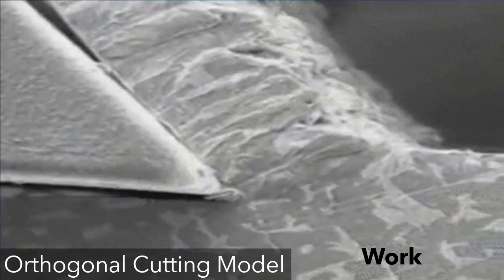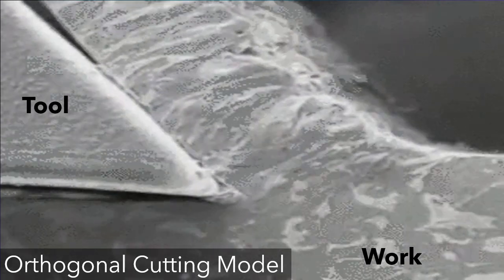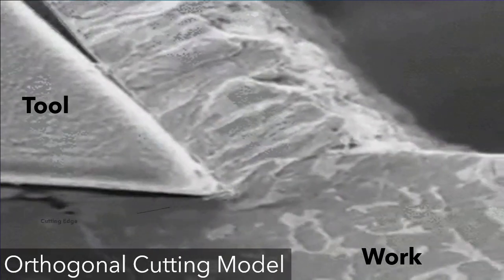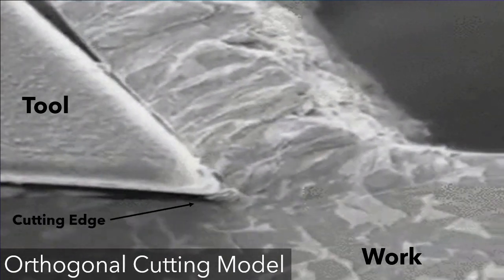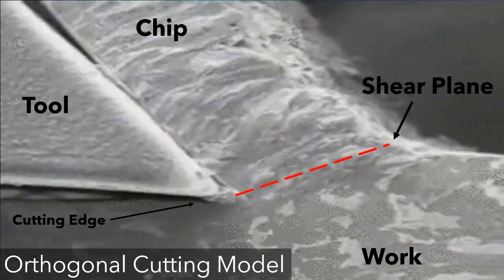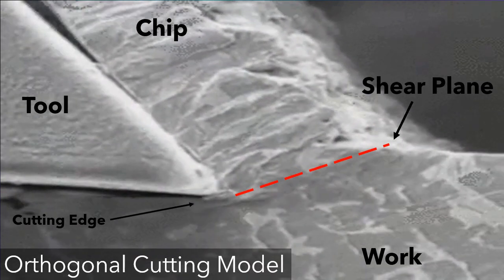The orthogonal cutting uses a wedge-shaped tool. The cutting edge is perpendicular to the direction of the cutting speed. The tool is forced into the material, and the chip is formed by shear deformation along a plane called the shear plane.